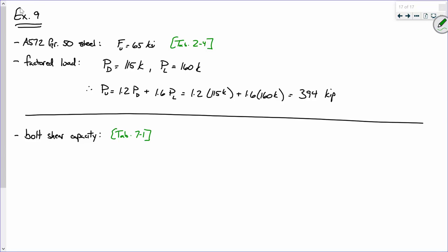So help me out. What information am I going to need to look up this quantity? Let's talk about the bolt diameter. What's the bolt diameter again? What group am I in? BX. Am I in single shear or double shear? I got single shear. Does anybody else agree with that? Good, that is right, because it is single shear.